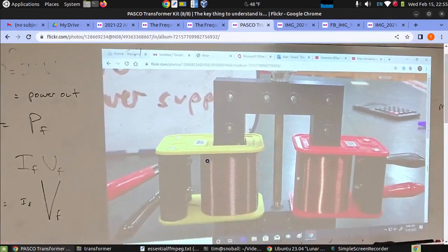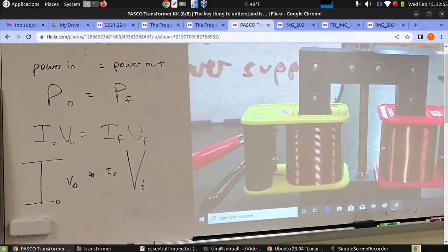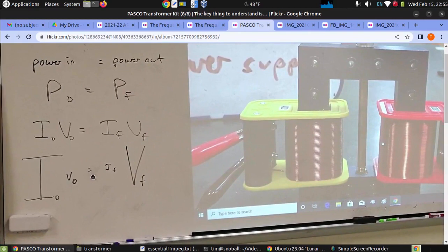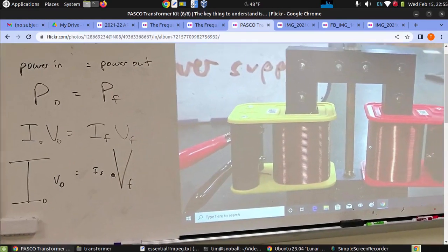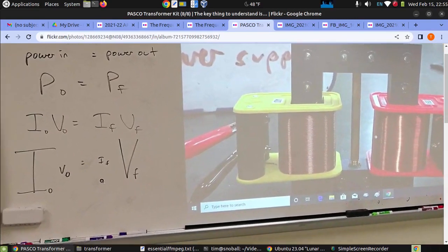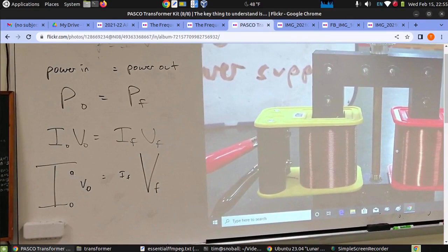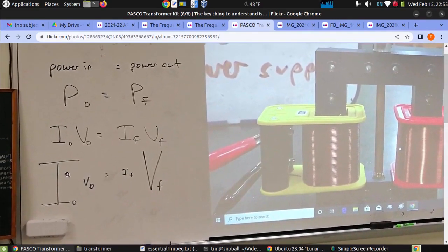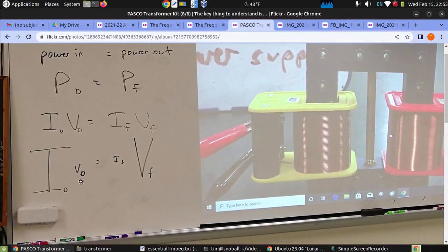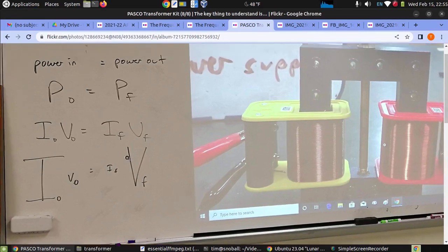So it would be really nice to be able to choose. In places where we want to transmit lots and lots of power and we don't want to waste money or energy, it would be nice to have large voltages, hundreds of thousands of volts, and relatively low currents. In places where people are going to access that power, we can put up with the loss of energy as heat because it means we can have the safer lower voltages. So every power plant births its energy at a certain potential difference. A transformer steps it up to hundreds of thousands of volts to send through high tension power lines.